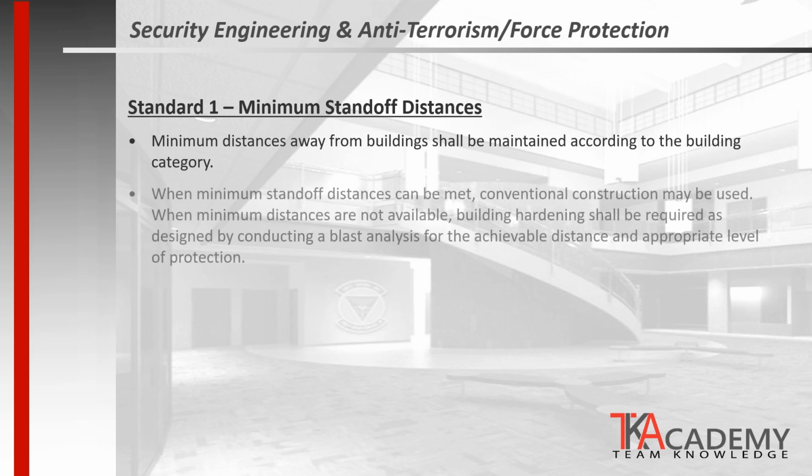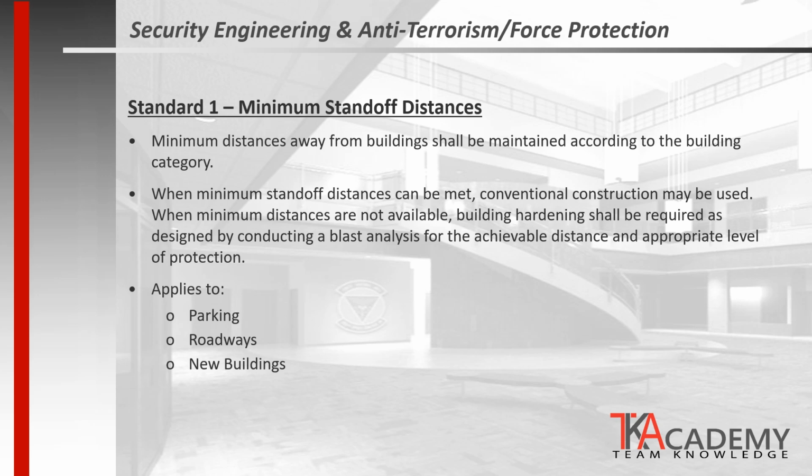When the minimum standoff distance can be met, conventional construction may be used. When minimum distances are not available due to limitations of the site, building hardening will be required and designed accordingly by conducting a blast analysis for the achievable distance and the appropriate level of protection. This applies to parking, roadways, new buildings, existing buildings, and trash containers.